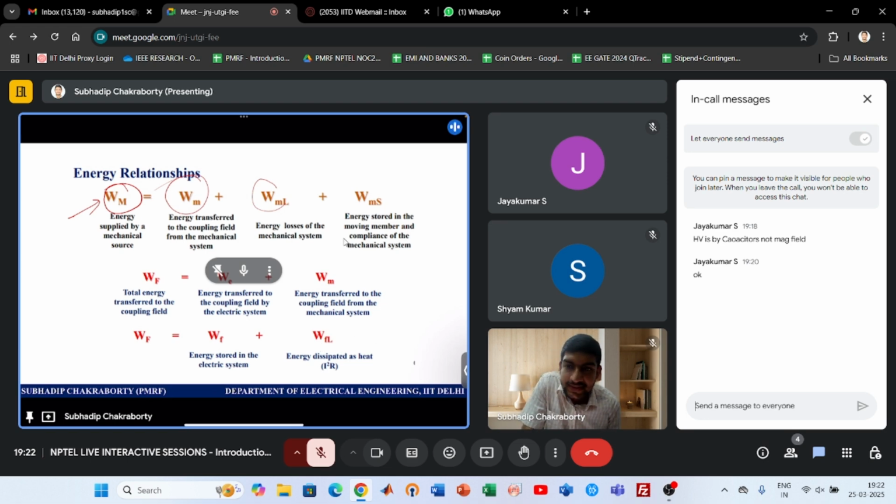They can be easily generated by just multiplying the number of turns. In place of 100, if you do 200, you get double the voltage. See how easy it is to create or generate such fields, right? And the application is also vast. In a complete machine, you will be using magnetic fields, right, for the electromechanical energy conversion.